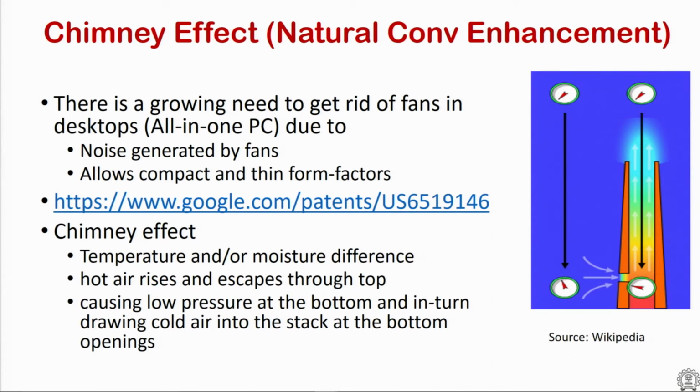In many cases, for example, the so-called all-in-one PCs where there is no fan mounting, they try to make use of what is called a chimney effect. What is a chimney effect? As shown in this picture obtained from Wikipedia, when you have a stack, a natural draft is established. As the hot air rises and you provide a much longer draft on top of this heated zone, the velocities get accelerated as the air rises through the chimney stack.